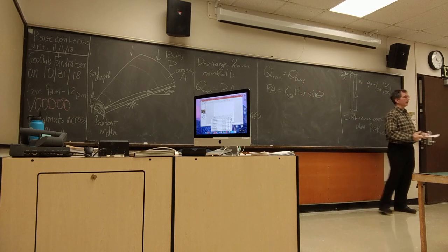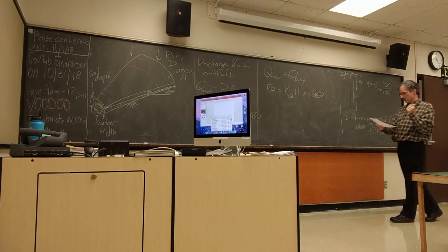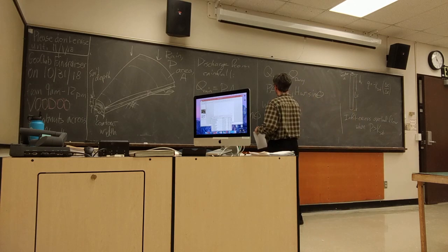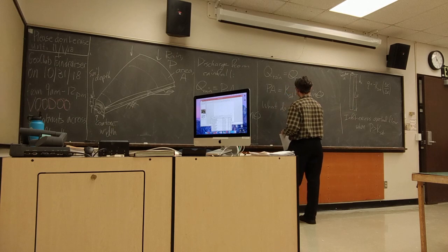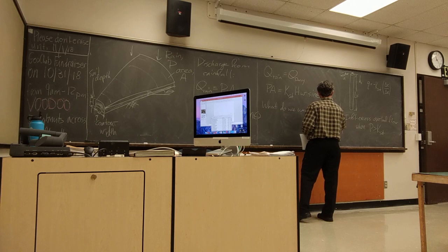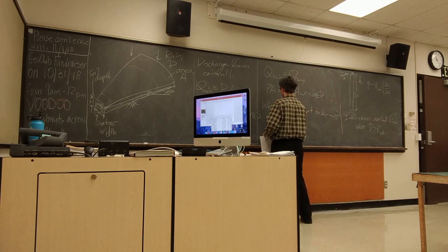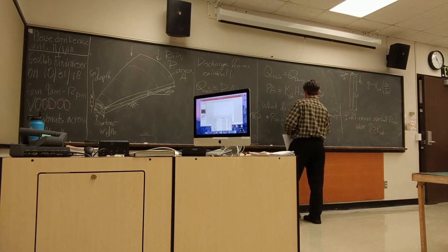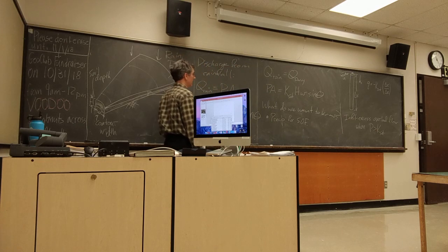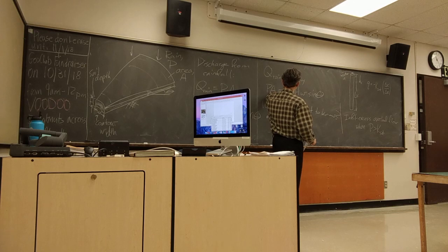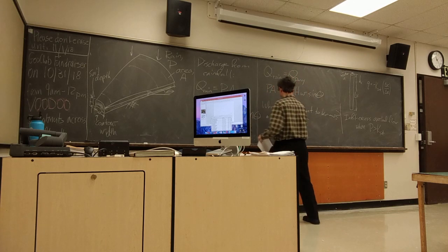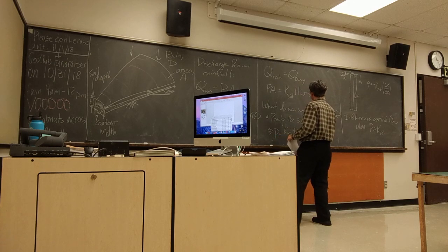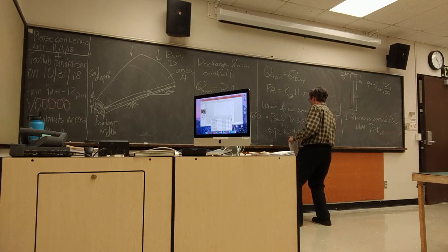And then I can say, what do I know and what do I want to know? Say I know everything except, say we want to know the precipitation rate for saturation overland flow at that given spot. Well, that's pretty simple. All I have to do is divide both sides by the contributing area. And we've got P equals Ksat, soil depth, contour width, sine theta, divided by the contributing area.